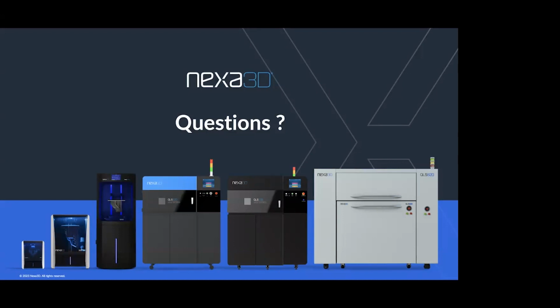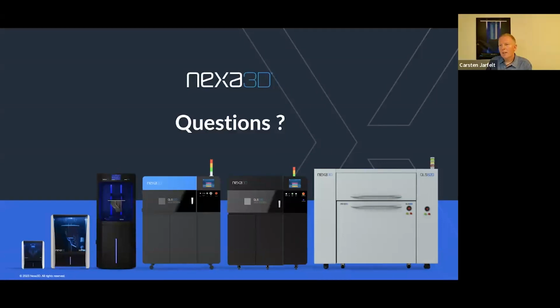Okay. Another great question regarding kind of technology comparisons. How does freeform injection molding compare to traditional urethane casting? I mean, it's often about, are you pouring stuff in? Are you squeezing stuff in using molding guidelines? And I think it's can you pack the material? Can you hold the pack pressure? Can you test the part for structural rigidity and life performance afterwards?